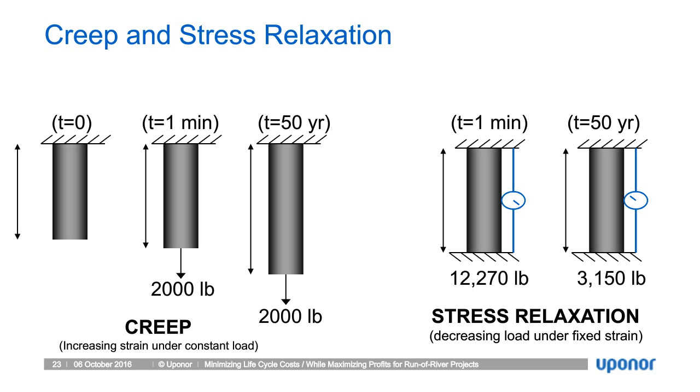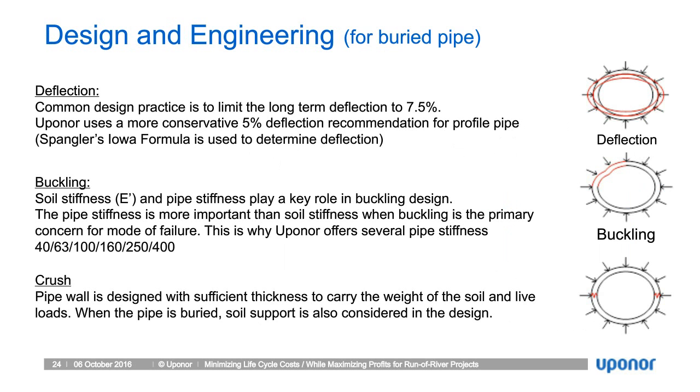And this is an important aspect if we do bury the material, and let's say some of the bedding or something is trying to push into the pipe, it will respond and the pipe will relax. If we have a material such as a rigid pipe that does not relax, and you have the constant stresses, the constant stress can result in a rupture of the pipe. So this creep and stress relaxation highlights that the material can adapt to its environment and reduce the stresses applied to it over time. That's a unique characteristic of the HDPE.